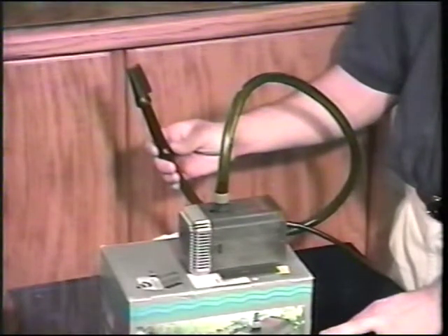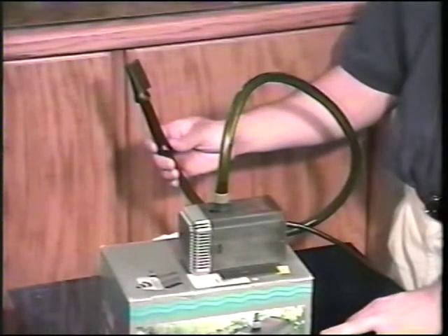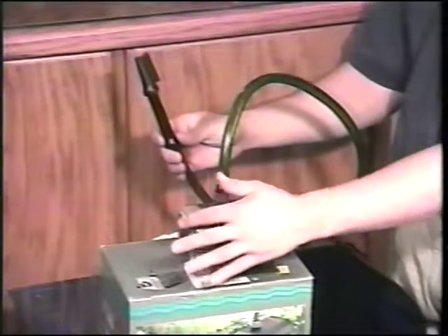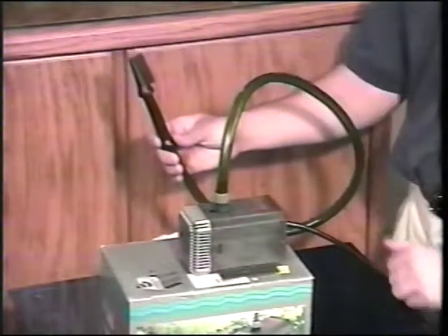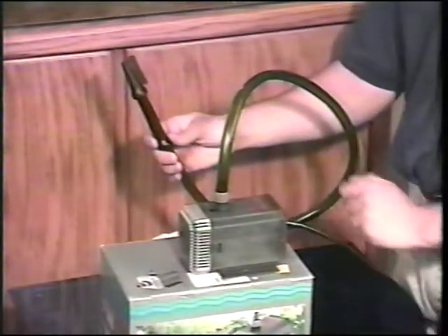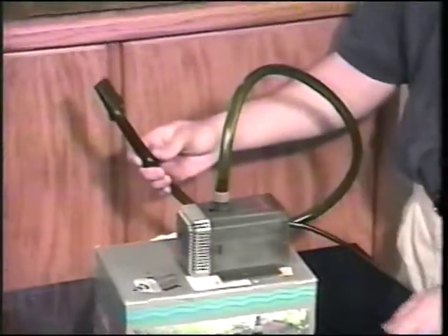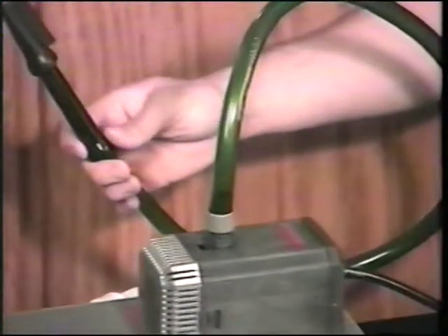As this water collects in the sump of the wet-dry filter, it is returned to the aquarium by a water pump. The water pump we have chosen is a submersible type, which fits inside the wet-dry sump. The water is returned to the tank by a spout, which creates current within the tank. The water pump should be capable of turning over your tank's water 8 to 10 times per hour.